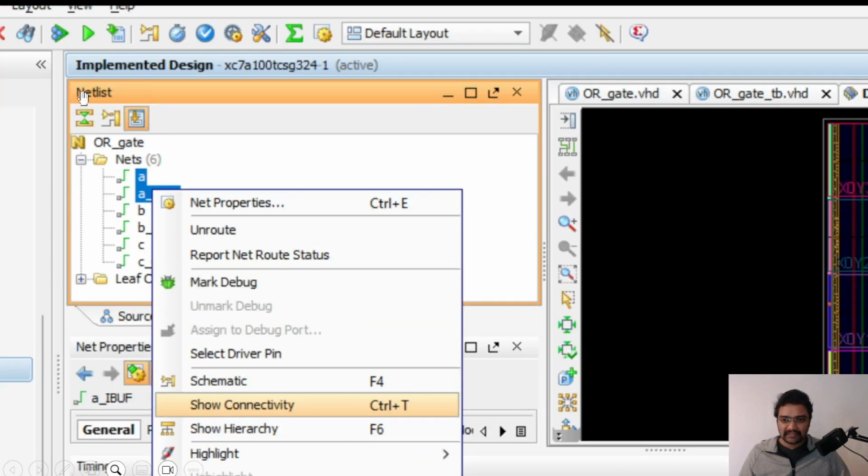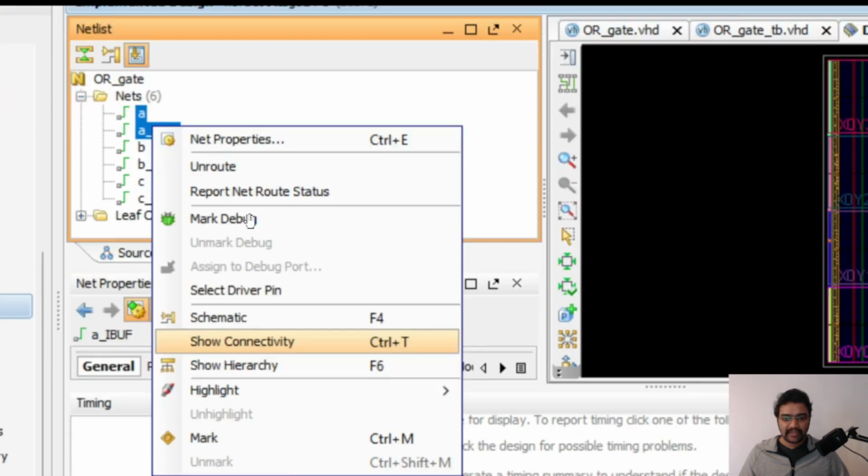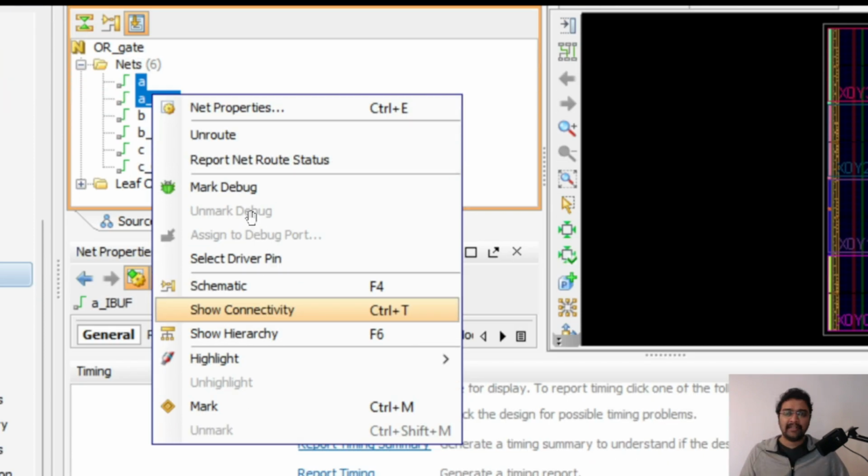implemented netlist. This is the netlist. A netlist is nothing but all the ports and the elements connected with the nets, and you can see these connections in the netlist file. This netlist file will declare the net connections, and if you select all these ports and right click, you can highlight them with whatever color you want.